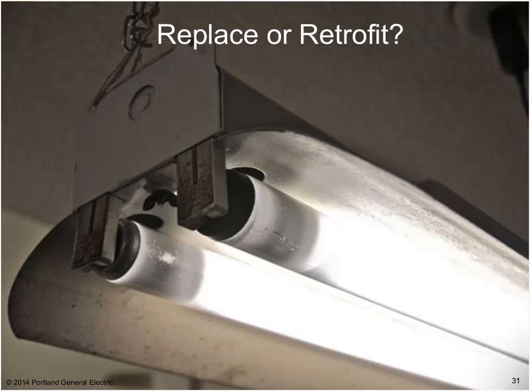Okay, so here we are out in the field again, and here's this industrial type fixture. So what are the clues that we're seeing here? Number one, we have a very discolored and dirty reflector, not really reflecting very much. The lamps are blackened, and at the very least, they need to be replaced.